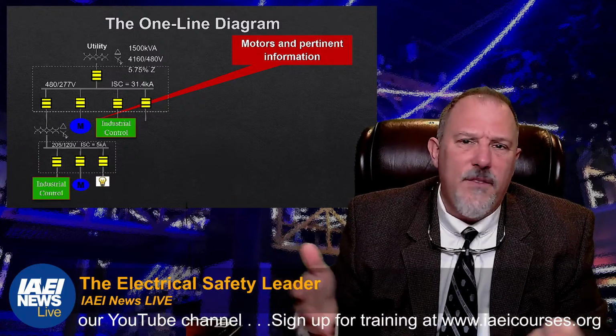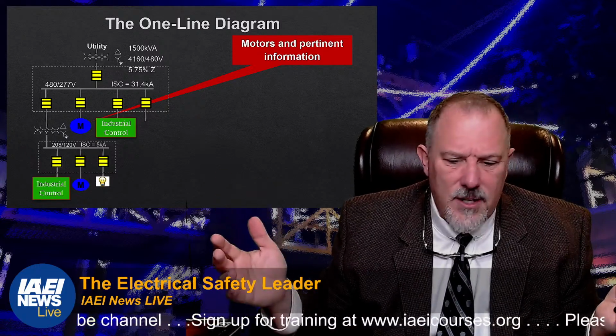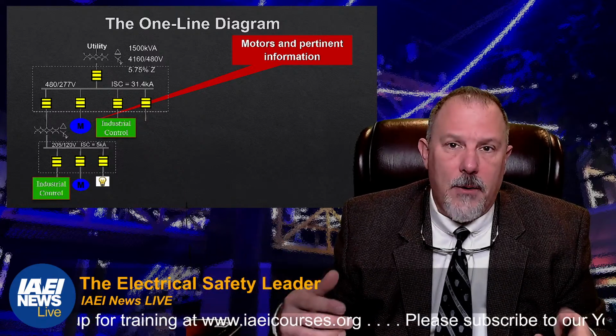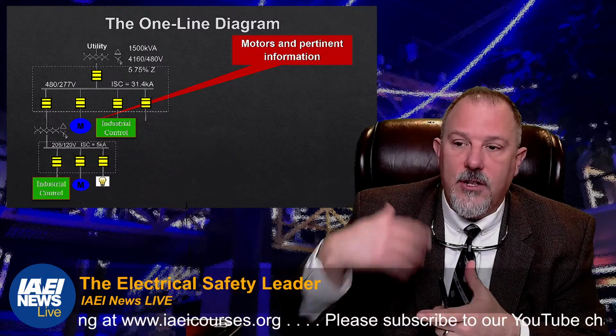20 horsepower, 25 horsepower motors, they'll say this is a group of 25 horsepower motors, and so we have 600 horsepower combined. Okay, and they'll model it as one motor.